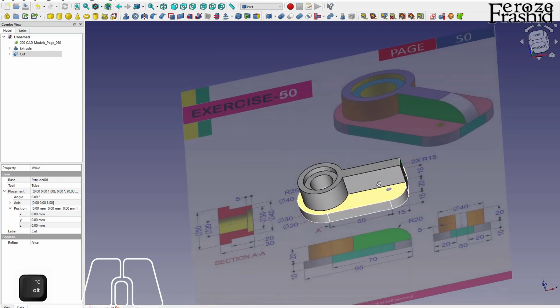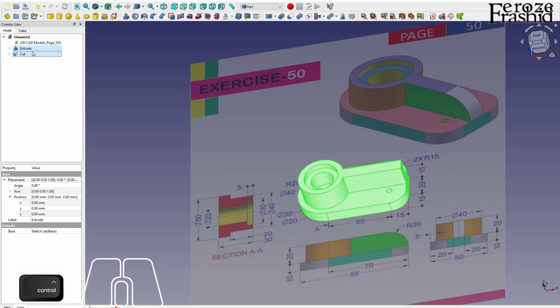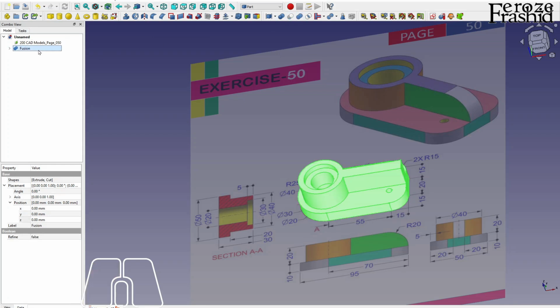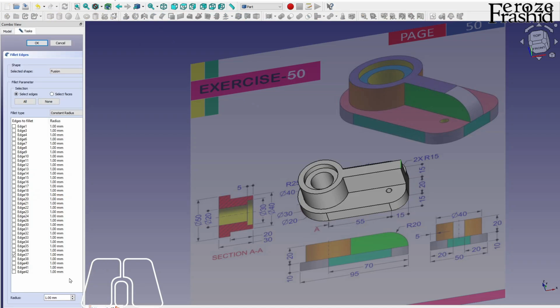And now finally, I want to make a fillet out of it. And before I actually do the fillet, I want to make these two one union. And then I want to refine it. After that, I want to do the fillet. So fillet comes all the way down the tree. The fillet radius is 20 and we pulled it up by 20.